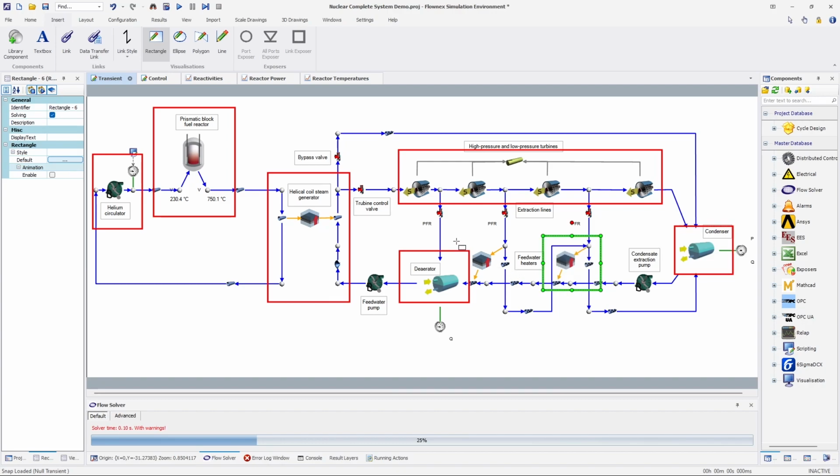The two feedwater heaters are modeled with composite heat transfer components to model conduction and convection. The feedwater and condensate extraction pumps are modeled with basic pump components. With these components, the required volume flow and head can be calculated for specific mass flow. The speed of this pump can be changed dynamically in Transient to simulate the changing performance of the pump at different operating speeds. The valves for the steam extraction lines were simulated with basic valves and were sized for the required steam flow rate needed for an energy balance.